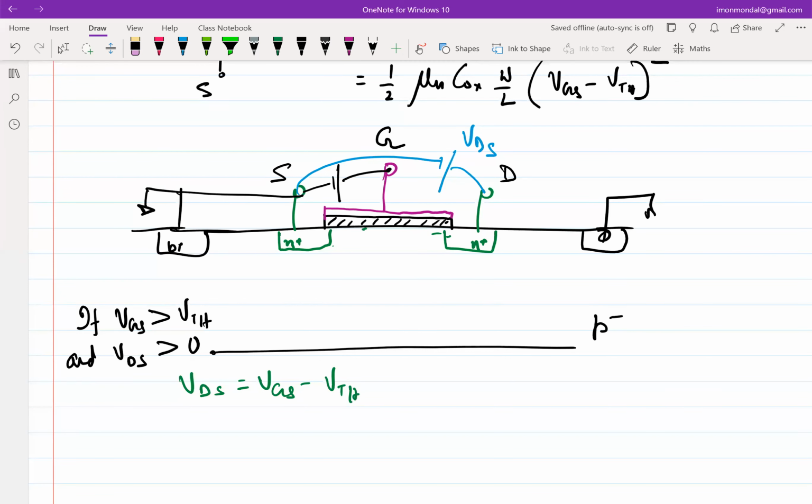So, okay, let's assume to start off, let me maybe spend a couple of minutes on this. Let's increase this size. So let's say VDS is equal to 0 and VGS is greater than threshold voltage, then there is no distinction between source and drain, correct? You cannot distinguish which is drain, which is source, which means whatever profile of the charge you see towards the source side will be identical around the drain side, correct? So you will have electrons uniformly distributed through the channel.